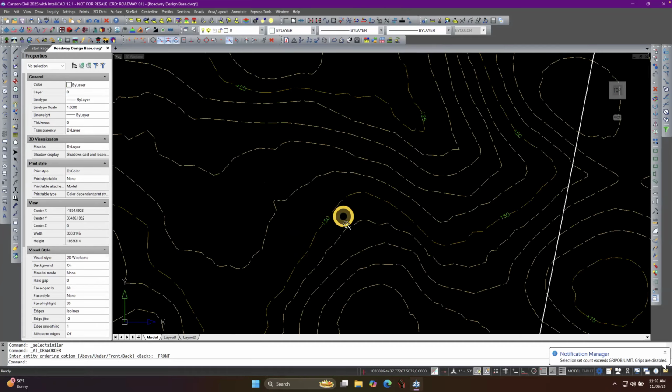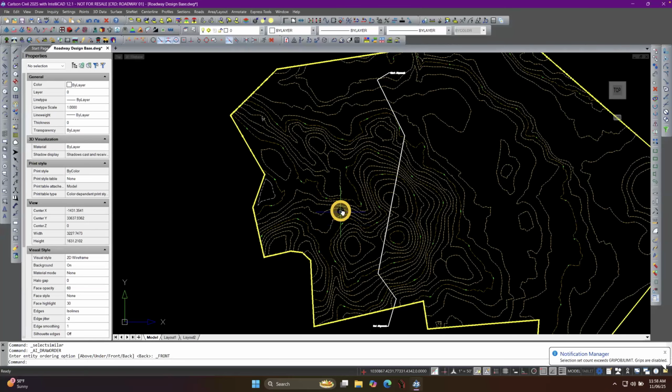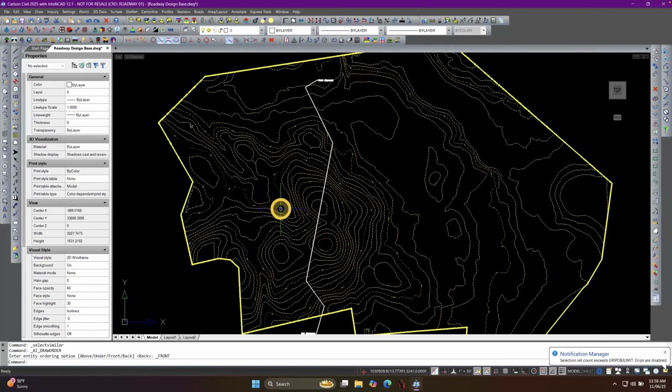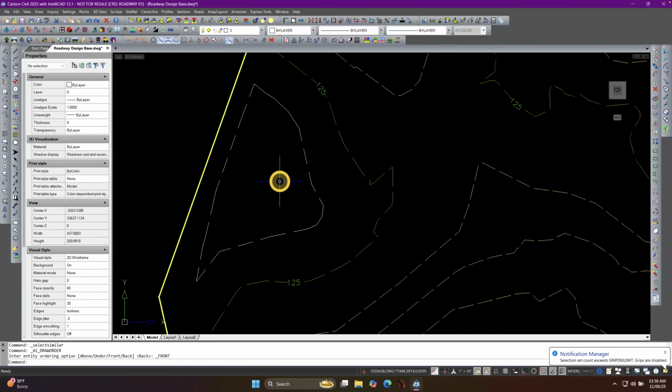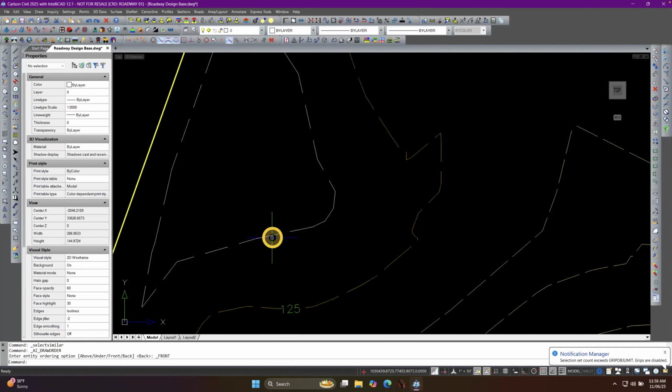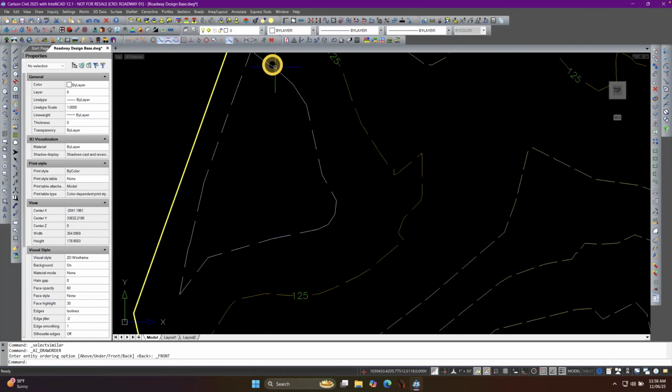Now, let's go back again because we had the very same thing that we did. Now there's your depression contour. Remember we told it to go on a different layer and use a different line style. Now there's an example of the right line style, but you see that it stays solid for this whole big long chunk.